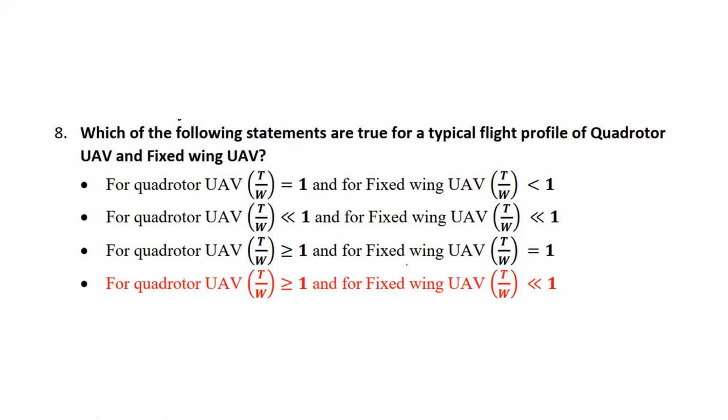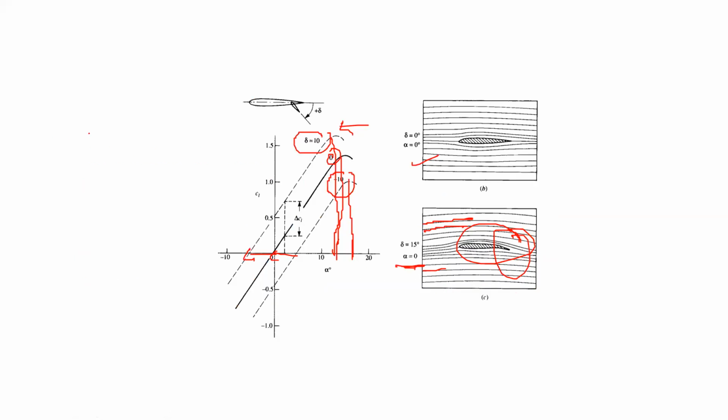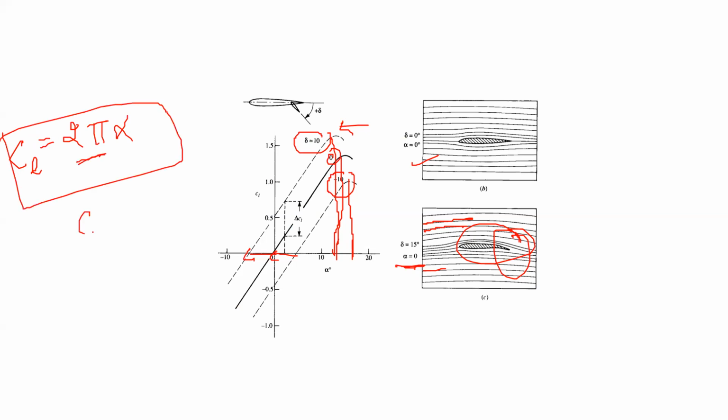When we study aerodynamics, this symmetrical airfoil turns out to be similar to a flat plate. They both have a behavior like this for CL. So 2 pi is that number. They call it lift slope, and this is a theoretically predicted number. So no wing will have a lift slope greater than this.